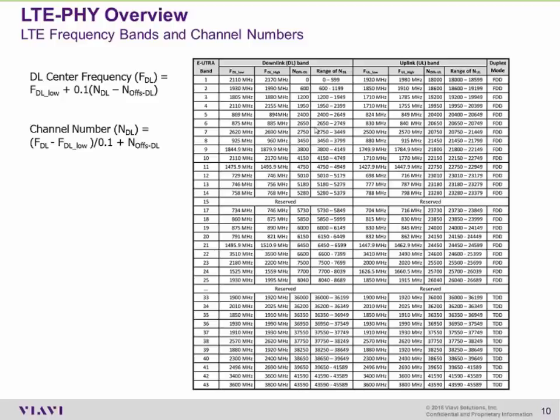In this slide, one of the things you may be missing is that this is basically just a reference to help you understand or navigate where the spectrum is. I highly encourage that in each one of the markets that you serve, you have some type of laminated cheat sheet that will quickly tell you where the centers are for your uplink and your downlink, as well as where your guard bands are, and whatever you refer to your channels as, F1, F2, however you communicate with others. Either way, you should be able to navigate, just like getting through the neighborhood to somebody's address. This is how you need to find your spectrum to be able to observe it.